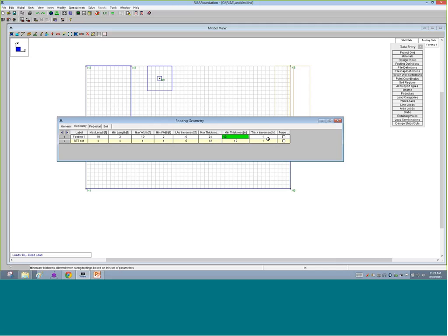So 12 inch, 13 inch, 14 inch, it will size up. Now, I can also force these footings to be square if they need to be. The pedestal is an input value. You just tell the program, hey, what is that pedestal? It's a 12 by 12 by default, kind of a nice default setting here with a 24-inch height.